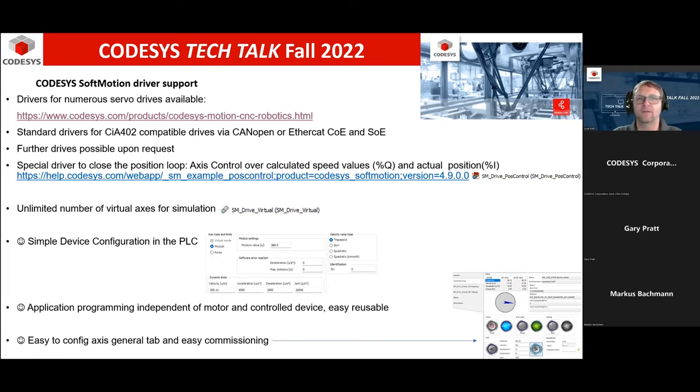If you have a set velocity, you're able to feed back in with a position control, such as an encoder, and then you can control the position of it, right? But keep in mind that that's really going to be based on your system. So you're going to have to know your loads, the kinematics of it, speed up and down, the weights, and really how good of torque your drive has, or whatever you're using the device.